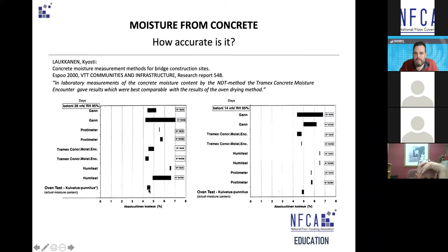This is gravimetric. For people who don't know what gravimetric is, it's the way that they measure moisture in wood or most building materials. Basically, you take a sample of the material you want to test, you weigh it, then you place it in an oven, usually over 100 degrees Celsius, which is 270 something Fahrenheit. You boil off the water and then you reweigh it. Sometimes they call it weigh, dry, weigh, because you have to go back and forth a few times.